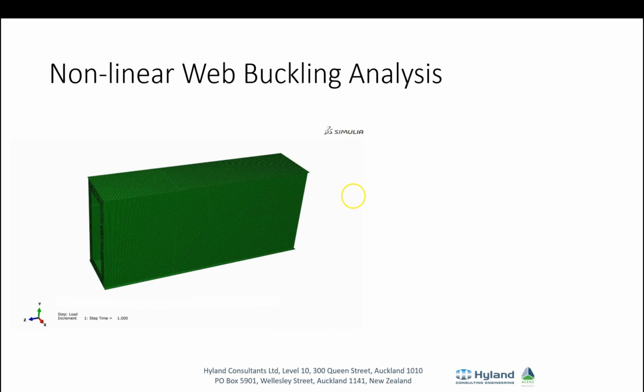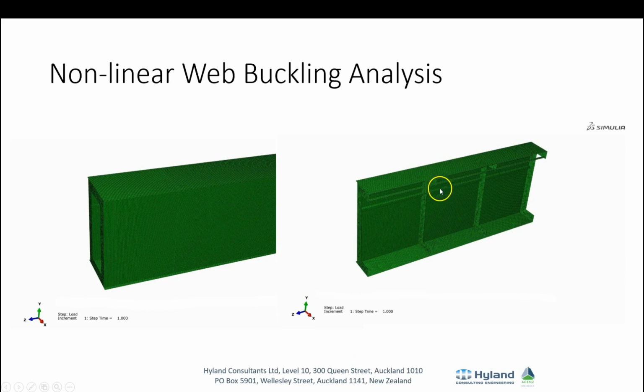It gave different answers around what the minimum thickness of plate should be in the web, the compression zone, and because 8mm had been used, this was outside what was allowed by AS 5100.6, but was allowed by the rules that the equipment had been manufactured to in Europe.